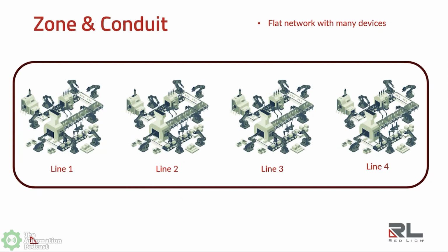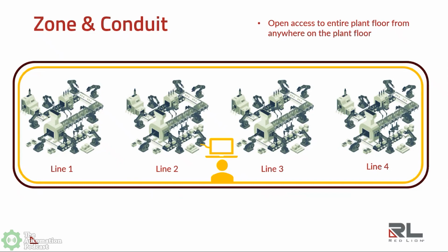The problem is that for a large number of our customers and a large number of industrial applications, that OT side is one large flat network. And like I said before, when you have one large flat network, everything can see everything else on the network. So you want to segment that and isolate parts of the network so that data doesn't flow freely unless you actually want it to. That is what the customer's problem was initially: when the contractor plugged his laptop in, it could see everything on the network.